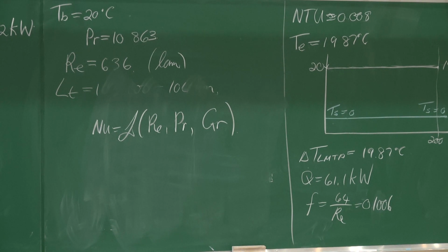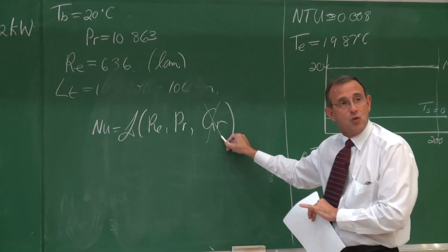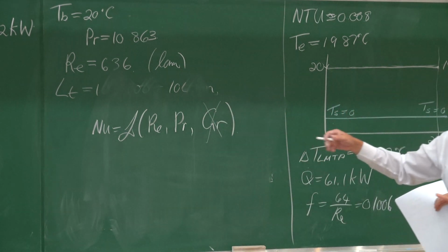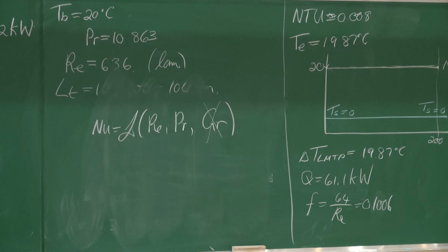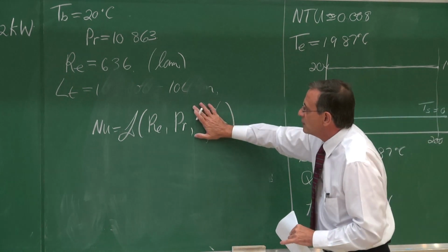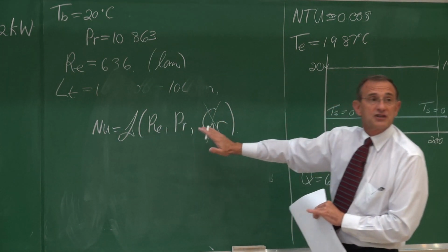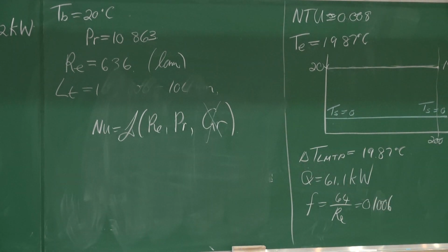So there are small changes in temperature and that causes flow changes. But in turbulent flow, this falls away. In turbulent flow, the natural convection is so small in comparison with the rest that in all cases, the Nusselt number is a function of the Reynolds and the Prandtl. And you will start seeing it here.